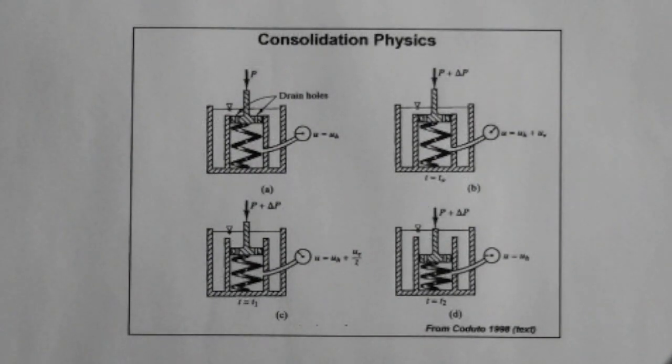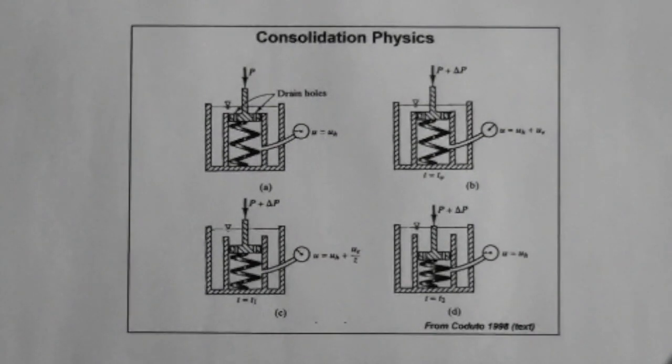This is the classic consolidation analogy that is used to explain how the water takes the load first as excess pore pressure, and then in time, as the water escapes, the excess pore pressure or load is transferred to the particles as effective stress.